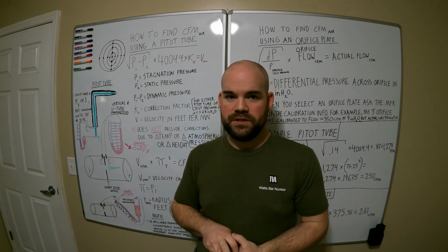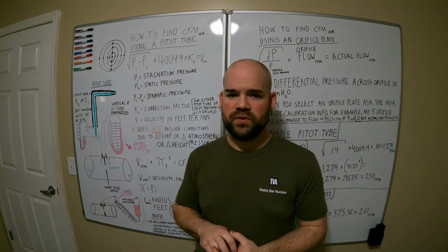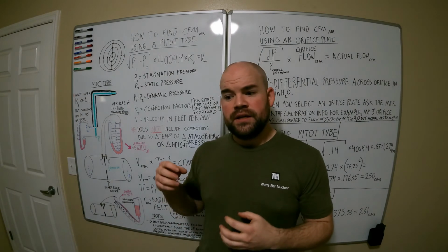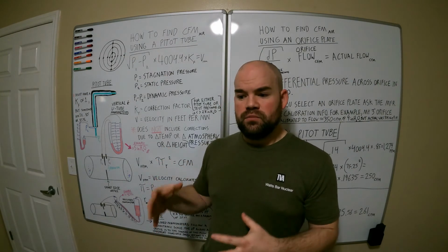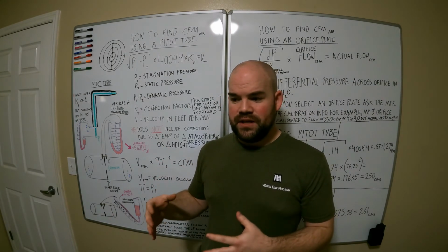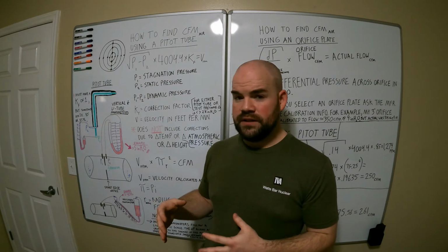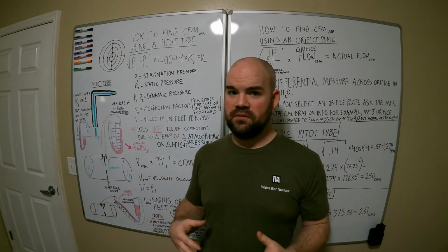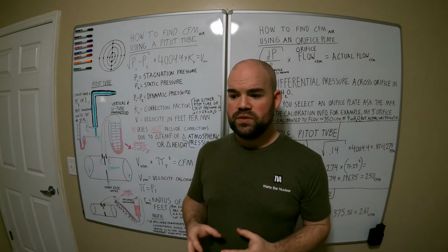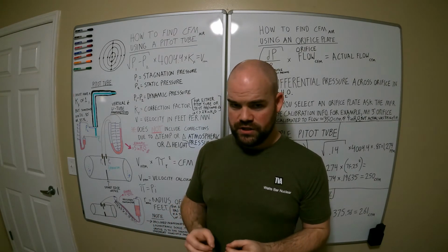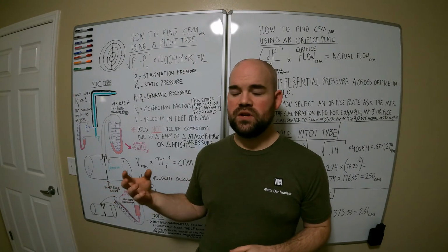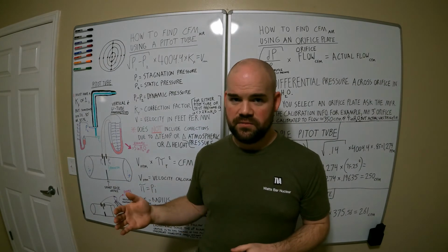I want people to understand that, because it's super important, and people think that flow testing is not that important on a boosted application. You want to build your engine as naturally aspirated friendly as possible, the most power you can make naturally aspirated, because it's only going to be amplified with boost. Boost is a measure of restriction, okay? Just because you have 15 pounds of boost does not mean the same thing on several different applications.